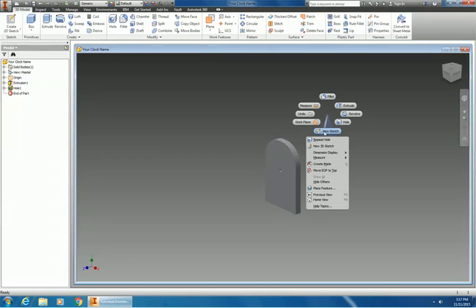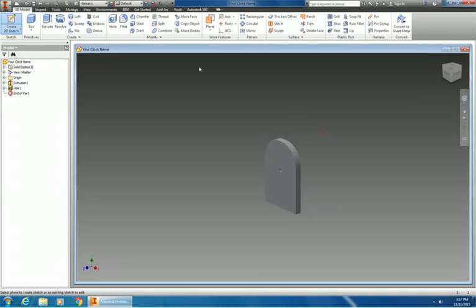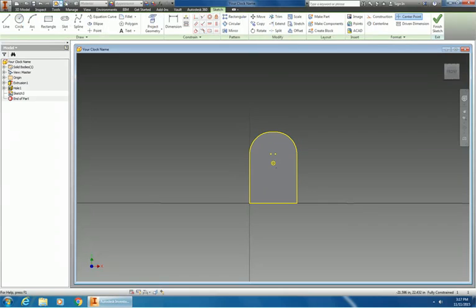Now we're going to create yet another new sketch. You can either do it from its top corner or from a right-click new sketch. You're going to select the face, and we're going to draw a circle. That circle we can snap to the center of our hole. It shouldn't really matter what size because we're going to dimension it. Your circle dimension here is going to be 2.5 diameter. Okay, that should do it for our circle there.